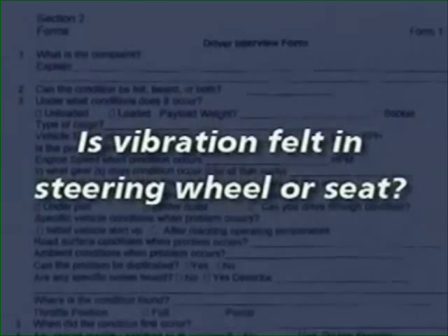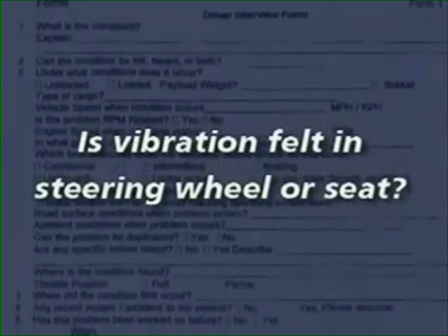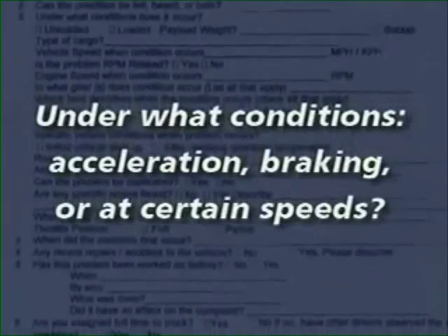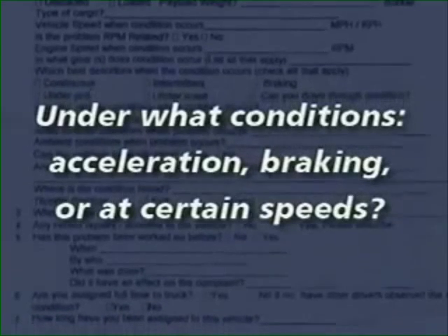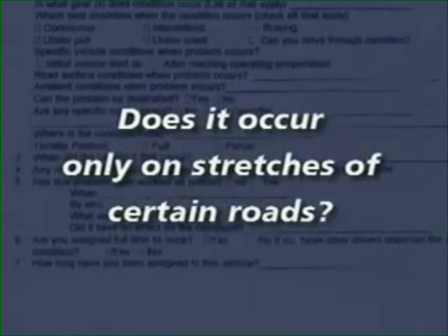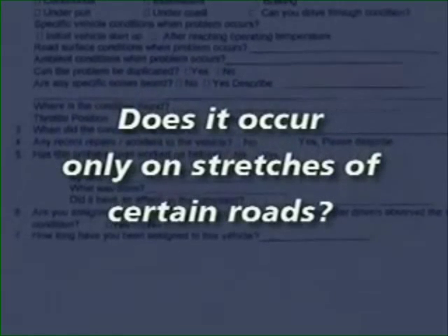Where is the vibration occurring, through the steering wheel or through the driver's seat? Under what conditions is the vibration occurring? Under acceleration, braking, or within a certain speed range? Is it occurring only on stretches of certain roads and not on all roads?